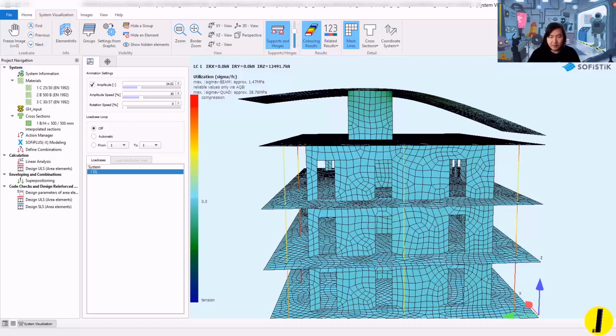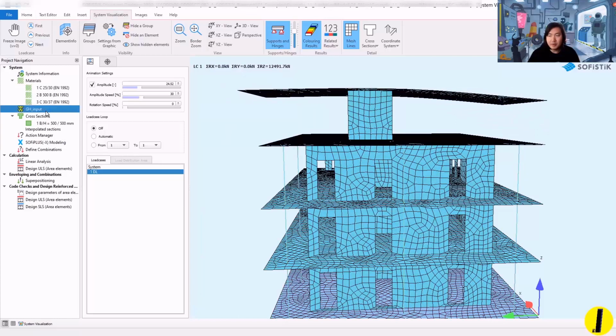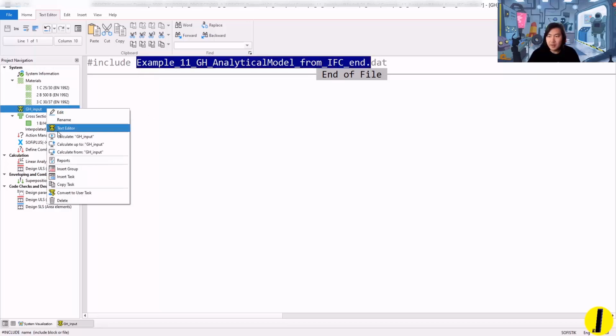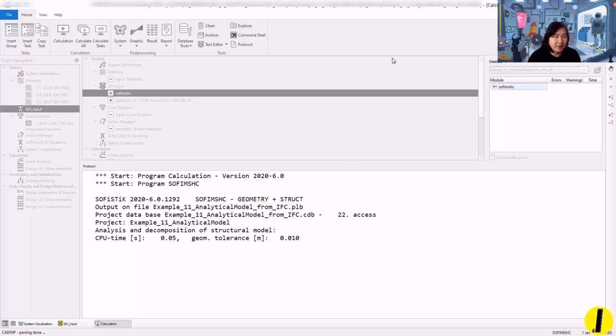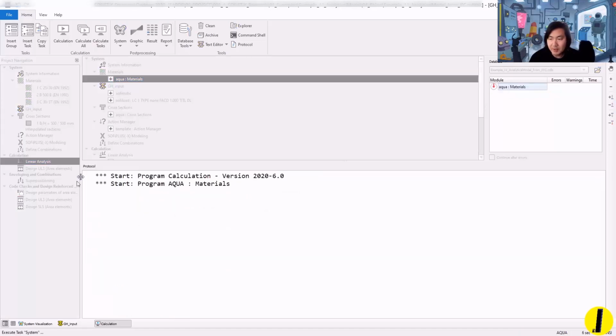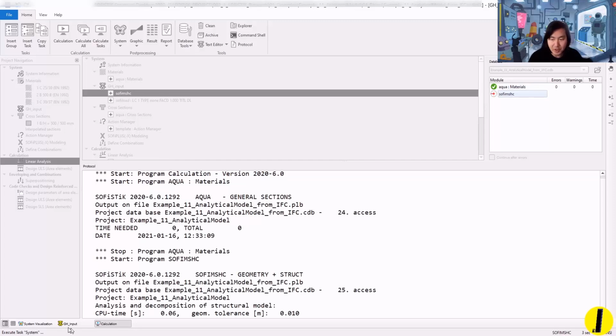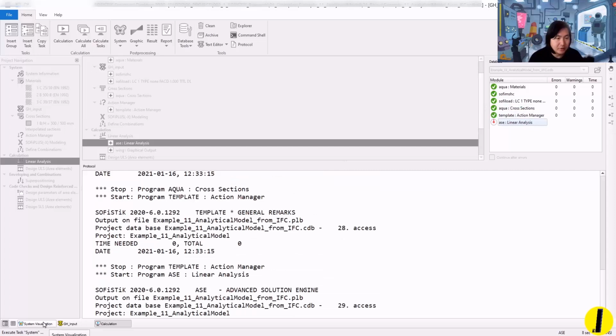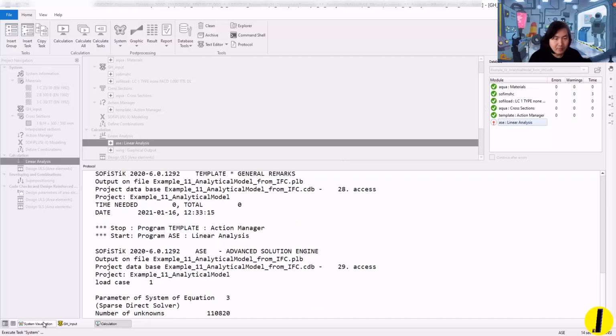So it's saved, and in SSD all I need to do now, I actually have to change its name, and let's calculate new geometry from Revit, from RhinoInside. And I have to calculate one more time linear analysis because we have new mesh from Revit, from RhinoInside. So we're gonna calculate new geometry now with this linear analysis. Takes a bit of time to calculate.